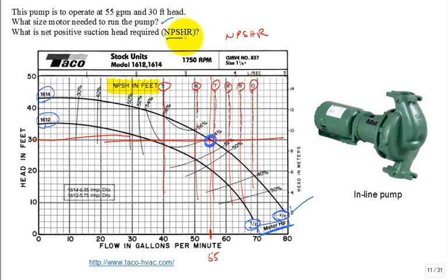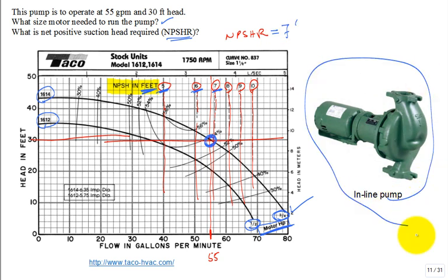And then the net positive suction head required, round off to the nearest foot. What is the net positive suction head required? Is it 5 foot, 6 foot, 7 foot? This is for an inline pump from that manufacturer. Basically, the pipe comes, you just need a boost. You could see that it's coming this way because it flows out and then turns and goes into the eye region, gets caught, thrown down and out.